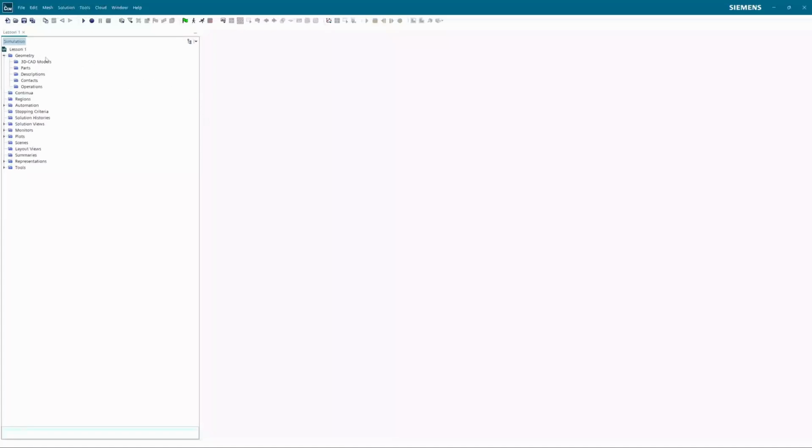So first, to start, all you're going to need is Star CCM Plus, and I will be using one STEP file of a wing. This is a file I created in Inventor, and I recommend you do the same. It is also possible to import points into Star CCM itself, but the process is easier in my opinion when you just import STEP files you created in another program.